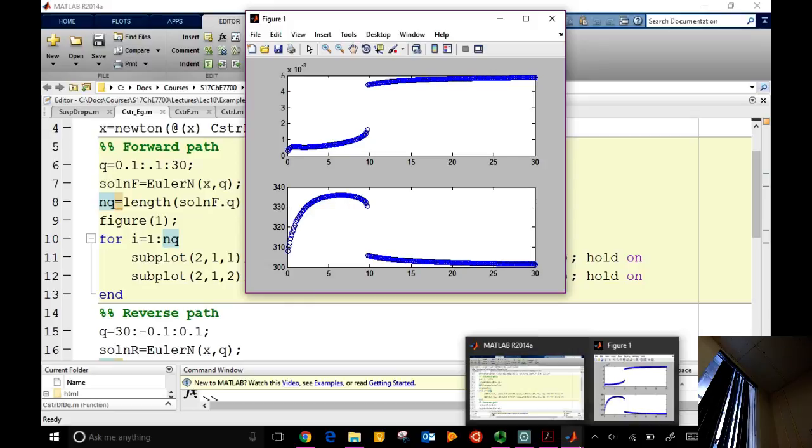It hits a critical value. One of the eigenvalues goes to 0 there. Okay, it becomes unstable. Everything funny in a nonlinear system that can happen happens around such a point. These are called the limit points. So there is no solution beyond the limit point. And we have seen an example of a canonical one-dimensional example where you have kind of a parabolic behavior around such limit points. Okay? So there is a solution here, and that will come around like this. But the Newton method, the Euler-Newton method, are not able to get that solution for us.